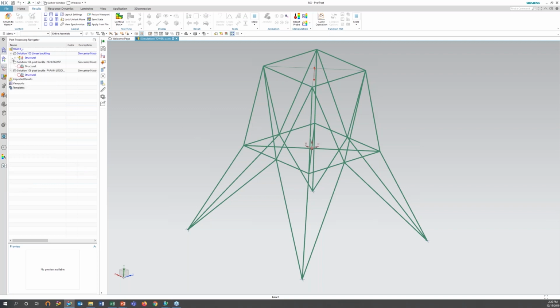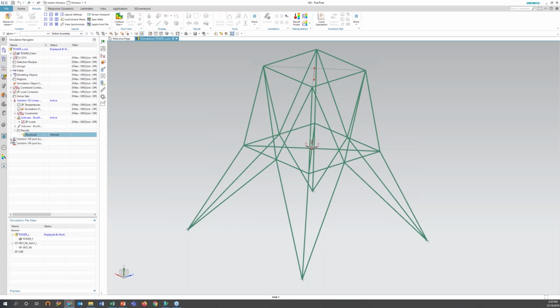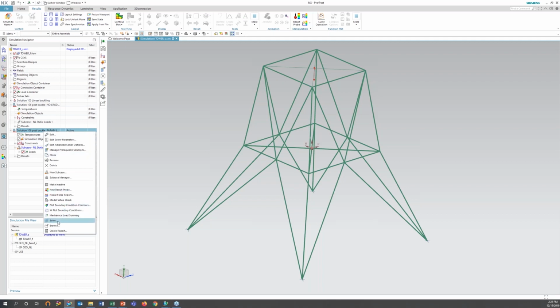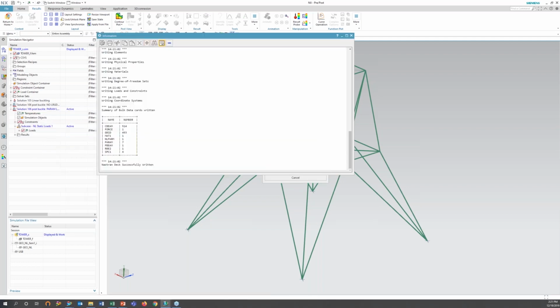So what I went ahead and did was I set up a nonlinear solution where I just want to push this thing through and see what happens after it has buckled. So I'm including this thing buckling out and I'm continuing to load it as it has buckled. All right. So I actually set up one without having the large displacement. And if you imagine you don't have large displacement, this thing's just going to continue to go down, go down, go down. It never buckles. So if you want to see it buckling, you need to make sure that you have that large displacement parameter turned on. I'm going to go ahead and solve that. And this takes a moment.